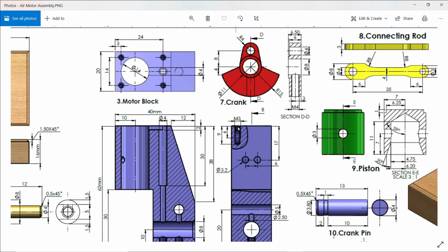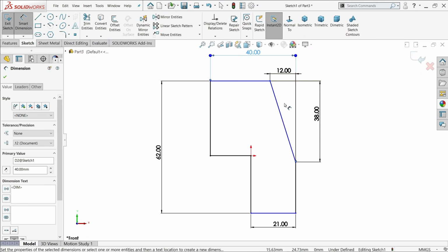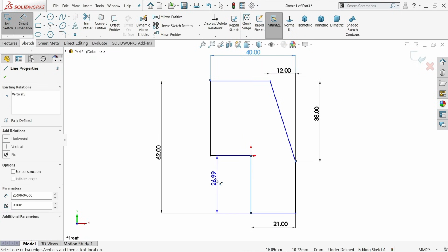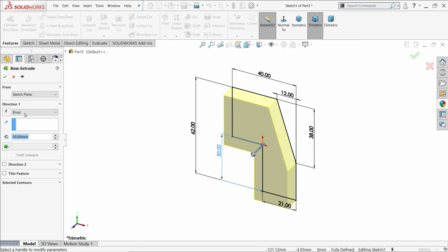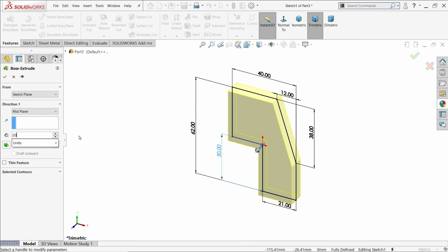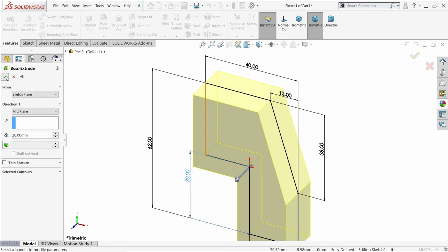And there are 4 tapped holes, M3, 6 thread, 9 length, and this is 14 millimeter, okay, 3 millimeter, 24, and this length. Okay, let's try this. Now this is fully defined. Extrude. Now here keep end condition mid plane 20, so that it helps us to create.